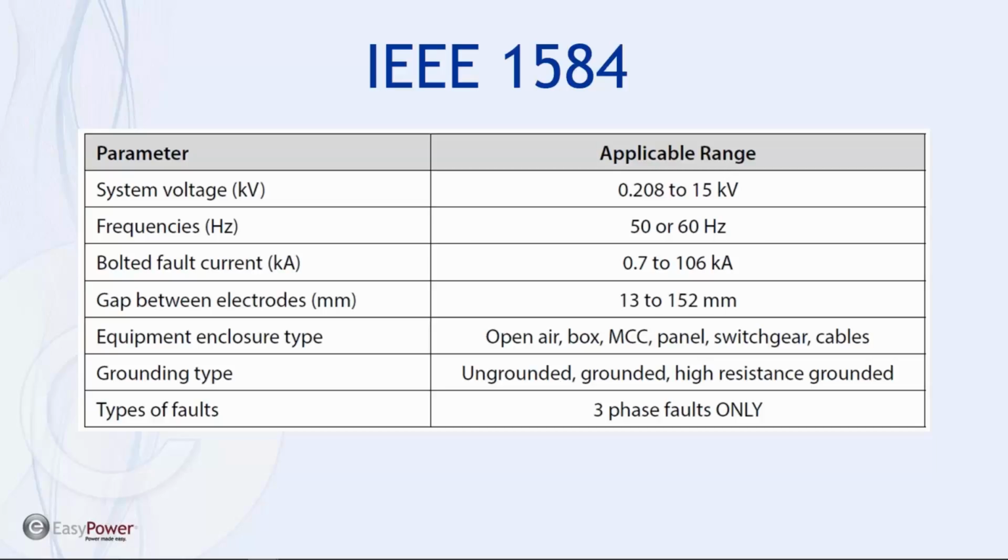And there's some leeway in terms of variability, and that's why both IEEE and NFPA refer to the solutions as estimates because of the variations that were seen in the characteristics of an arc itself. So there's always a tendency to lean towards a worst case situation, which would include some guard banding in terms of personal safety.